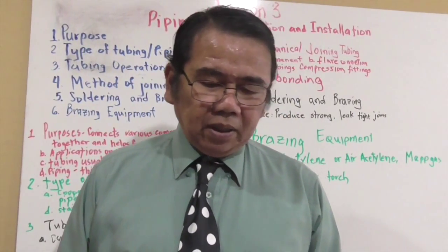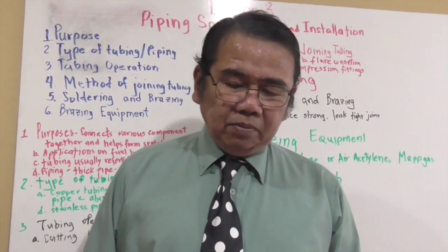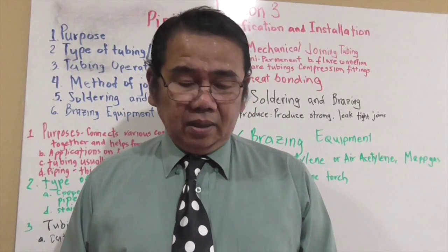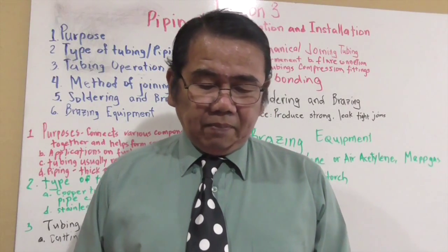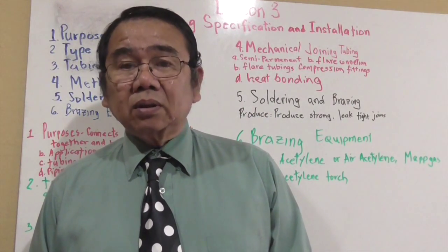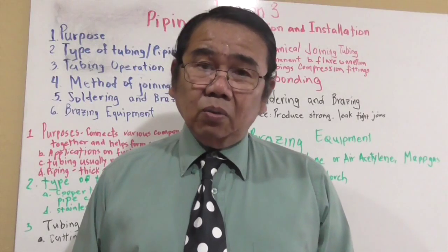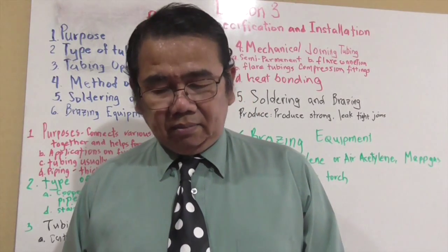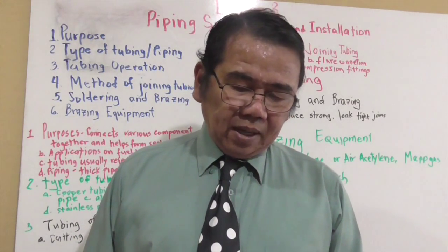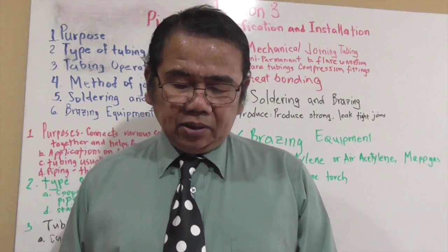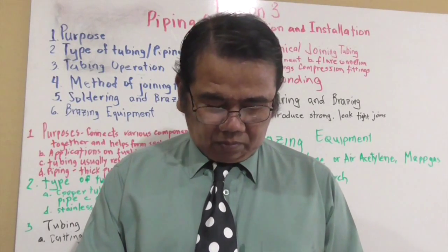The four steps of preparation continuation. Cleaning the tubing and fittings. Surfaces to be joined must be free of oil, grease, rust, and oxide. Clean with cleaning solvent. If really bad, use a wire brush or fine sand cloth. Do not use steel wool. Use emery cloth, sand cloth. Do not handle surfaces after cleaning. Cleaning should be done just before soldering to keep oxidation to a minimum.